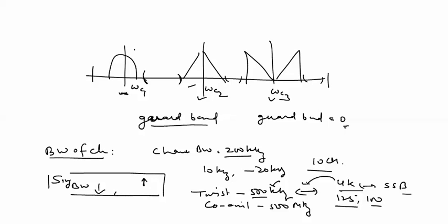If our basic signal is a video signal of megahertz bandwidth, we cannot accommodate it in twisted pair, because a video channel has larger bandwidth than twisted pair. So we have to use coaxial cable, which can accommodate 100 TV channels. That's why coaxial cable is more suitable for TV transmission and twisted pair is suitable for telephony. I took one example.